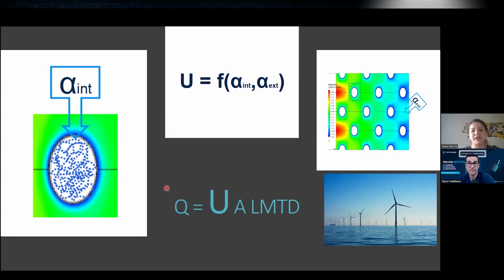Yeah. Because the saltiness of the environment can cause corrosion in the aluminum fins, and you will have a short life in your heat exchanger. But if you consider a coating, the heat conductivity of this fin will be smaller than the one that doesn't have a coating.